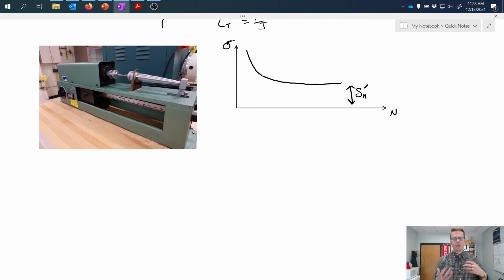So we might reduce that limit on the basis of how the loading is applied, the size of the component, the surface finish, the temperature that it's going to be operating in, and perhaps just reliability. Because as it turns out, the prediction for when this will fail is just that.